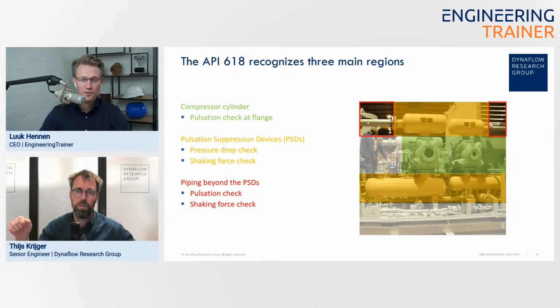So if your compressor runs at 14 hertz, then the frequencies that you need to come up with in that level 2 check are way higher than the 12 hertz suggested in the Energy Institute, I guess. Yes. That would boil down to 14 times 2 plus 20%. Those are quite high numbers to remove eigenmodes.